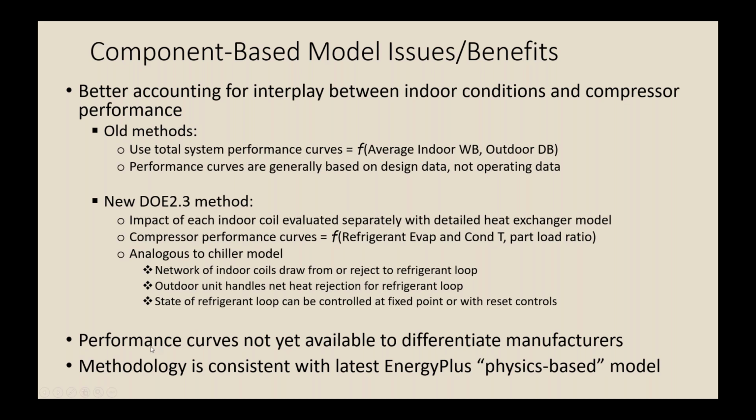So one issue with this approach is that performance curves are not yet readily available to differentiate one manufacturer from another. The default curves that come with the program are, I think, reasonable and give a fair analysis of a typical VRF system. But if you're trying to compare one manufacturer to another, that doesn't necessarily give you the ability to do that because the manufacturers don't have that data yet. You can compare one efficiency level of equipment to another, and I'll get into how you do that in a little bit.